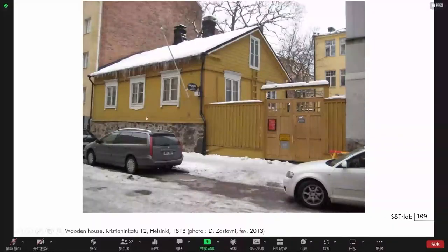You are protecting timber from the ground with stone. You are protecting the highest part of the roof with timber. We have several elements that will be putting the water away from the element. You have places that could be replaced, and this is protected with stain. This is not a paint, but a mixture of oil and paint in this case. And there are parts that will be different, that could be replaced, and others that will be maintained. So that's the kind of element.